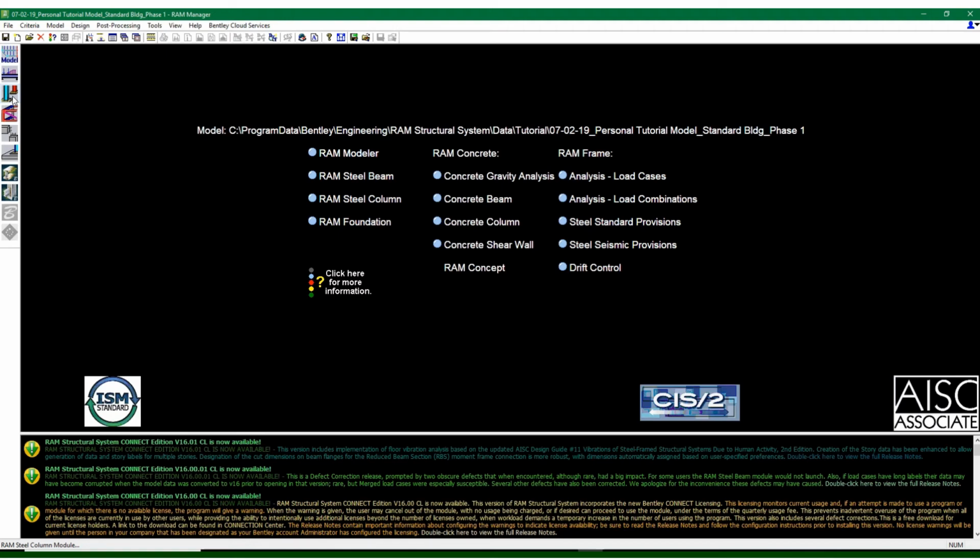Even though you'll have lateral columns and beams in your model, when these members are designed in these particular modules, beams and column design, it only takes into consideration the gravity loads that are imposed on your structure and not your lateral loads for earthquake and for wind or for notional loads or any other lateral load that you may have inserted into the structure.